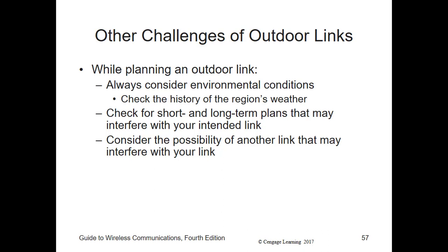The possibility of another company or a person setting up a link in your area, which could interfere with your radio frequency, could be a concern. If you're using unlicensed frequencies such as ISM or U-NII bands, you can't count on assistance from regulatory agencies or authorities. So of course you always have to make sure that you're not interfering with anyone else's signal before you set up your outdoor link.